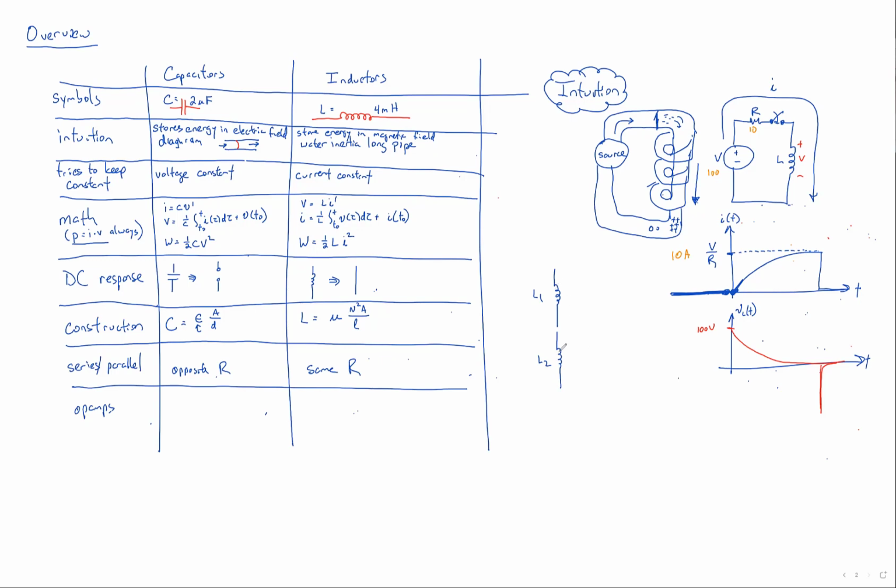And so it's going to be the same as a resistor. Inductors in series add, and inductors in parallel have that weird 1/over relationship. And let's just talk about that, because I had a question last night about this. What is this 1/over relationship thing? If you have 3 or more inductors, the equivalent inductance has to be figured out by this equation. I mean, you could add more and more of them over here if you wanted to.